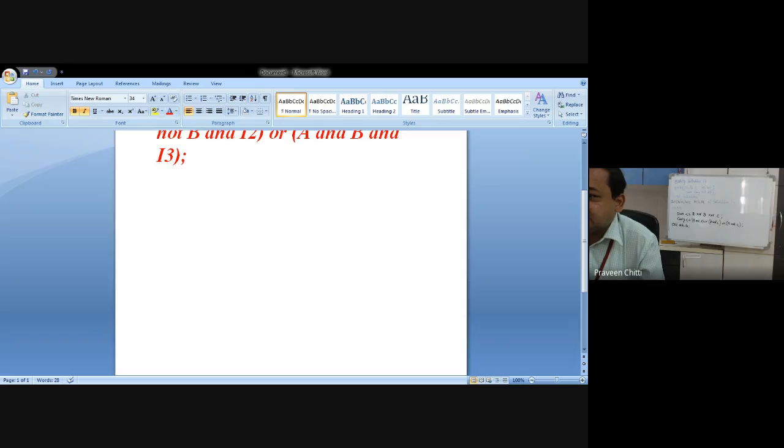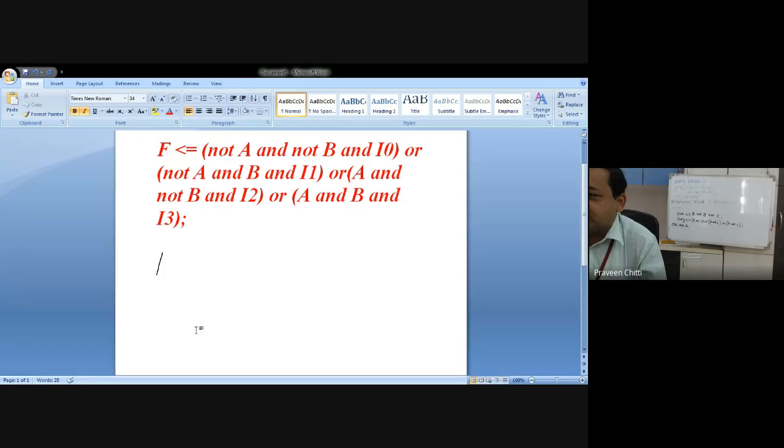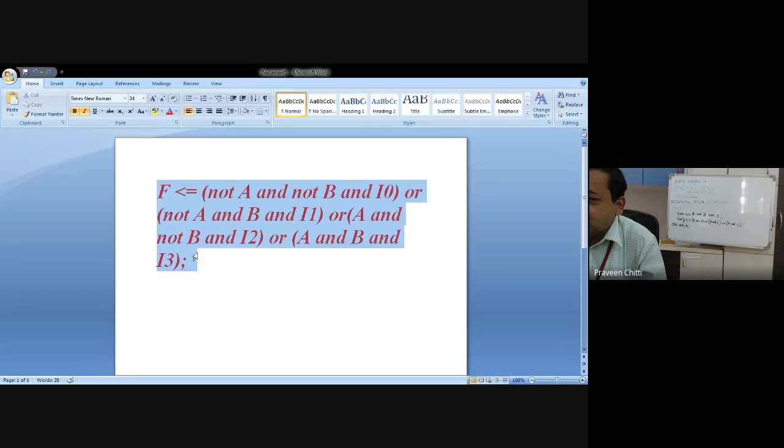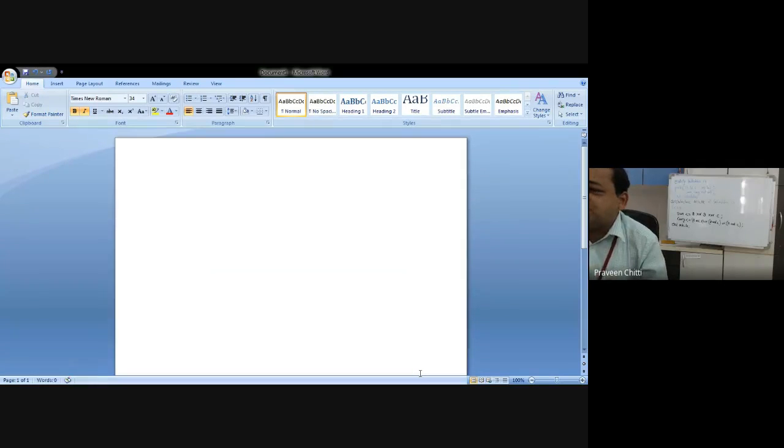And which is the selected signal assignment statement? It is the with select statement. With select statement is called selected signal assignment statement. And I told you to write the VHDL program for the same 4:1 mux using selected signal assignment statement. So what change should you make in this program? Everything remains the same. The single equation you have written has to be deleted, and in place of this, what you have to write now?